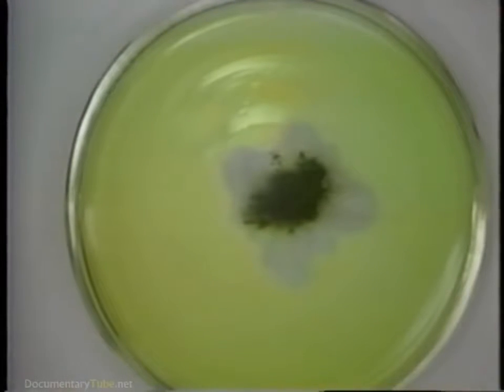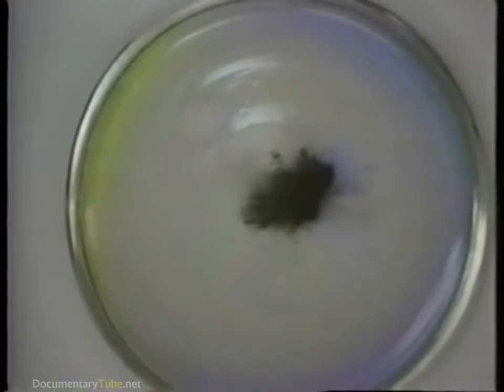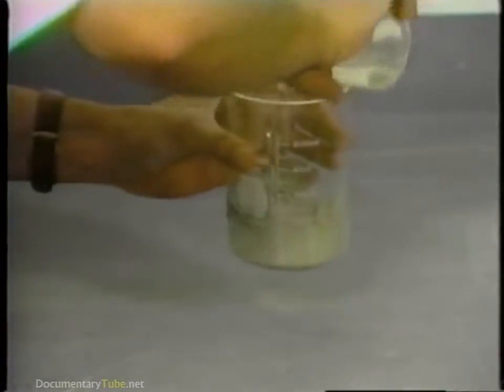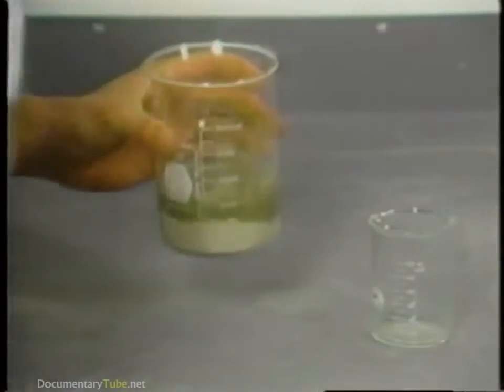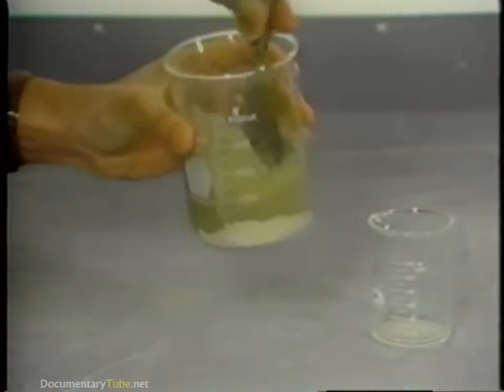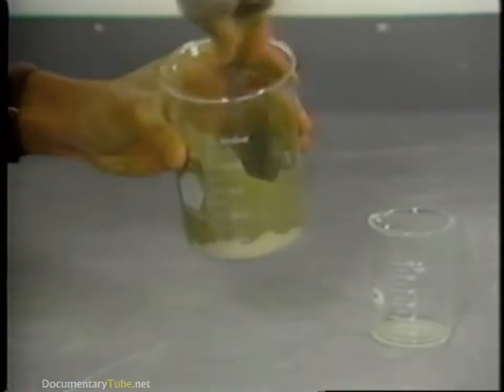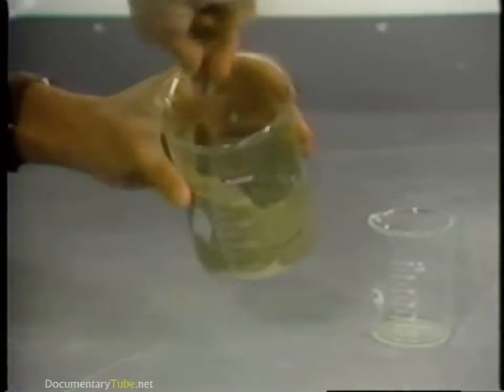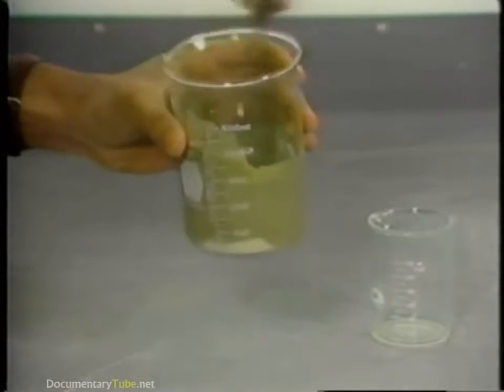This can be demonstrated by adding a small amount of cement to water containing an indicator. The rapid development of a blue color reflects the release of hydroxyl ions from the dissolving cement. The chemical reaction between cement and water is called hydration. The dissolving cement increases the levels of calcium and silicon in the solution. When the concentrations of dissolved species reach critical levels, new solid products are formed through a precipitation reaction.